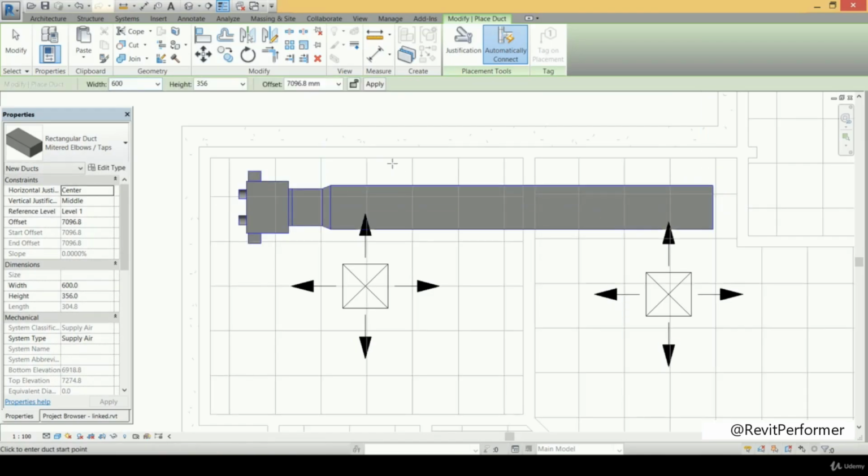That's it. And here we do that linking operation because that design reduces the air noise and the disturbance inside the main duct. Also, this linking duct enables us to put insulating material inside that part of the duct that is nearer to the VAV box, so we can reduce the noise, as we said before. And we may also use that part of the duct with the same dimension to put any controlling element at that position, like dampers, so we are getting the benefit from that linking duct for those reasons.